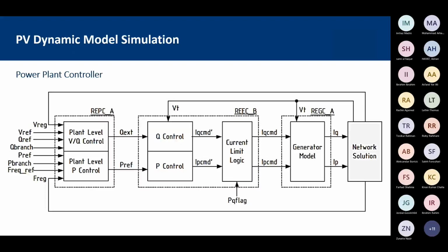So that's why we need to use these controls or these kind of ride-throughs, so that instead of being a burden on the grid, these systems can support the grid. So that's why when we're doing dynamic modeling, that's one of the key components we need to look at in our studies: how does it respond to certain frequency disturbances.